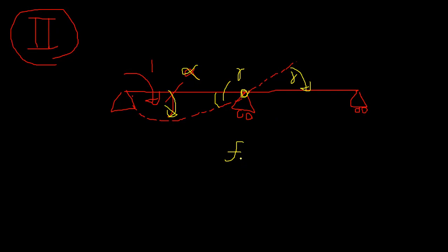Displacement at first coordinate due to the unit redundant at second coordinate, theoretically this is equal to F21. If it is not, you might have made a terrible mistake, because according to Maxwell's theory, F12 and F21 are exactly equal with the sign as well.